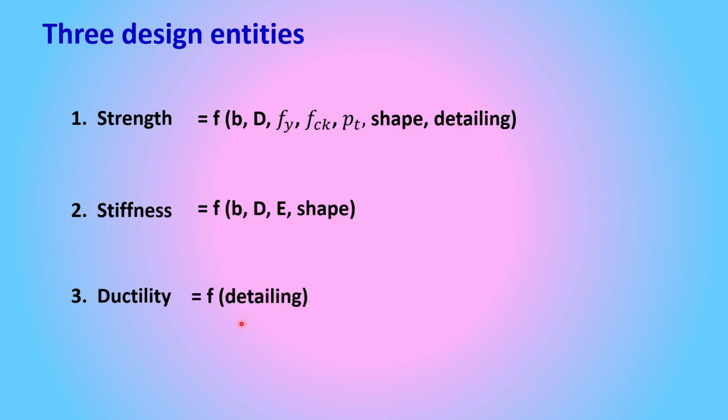Ductility is actually not affected by all this generally, but it depends on the detailing and disposition, both in concrete structures and steel structures. In steel structures, you have to pay attention to the joints specifically for a ductile system. And in RC structures, the country codes are there which will give you the detailing requirements so that the system is ductile. Though a little effect will be there of the depth of the section, we will see later on that depth will be affecting the ductility also.